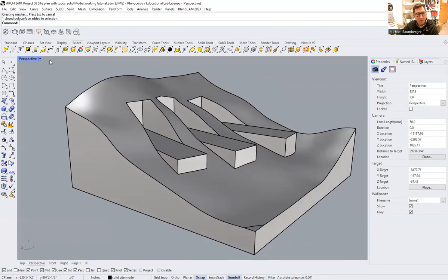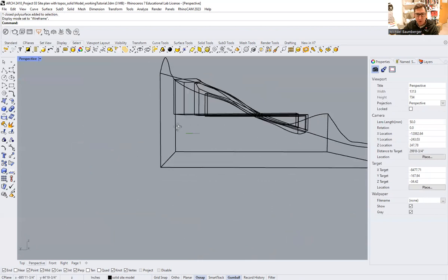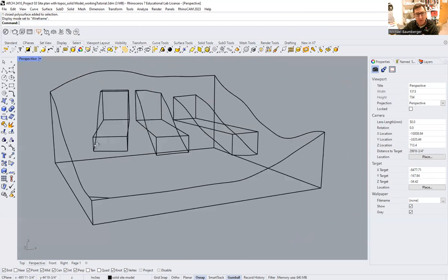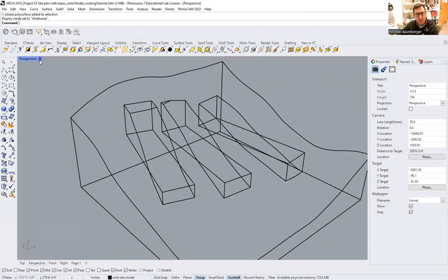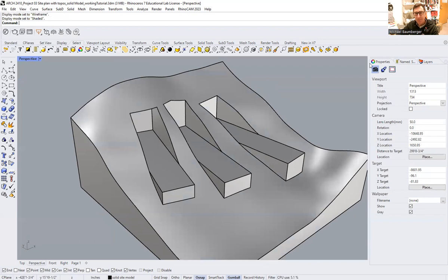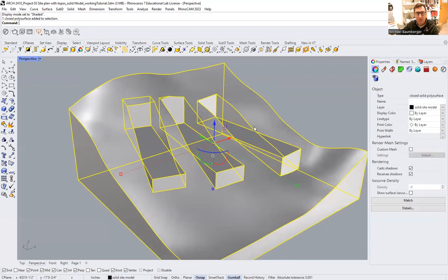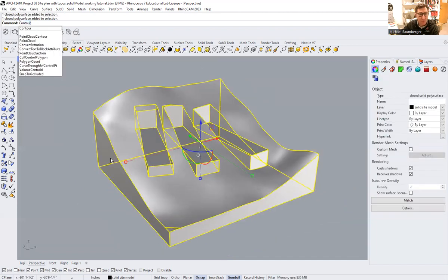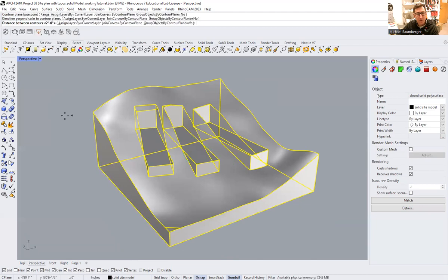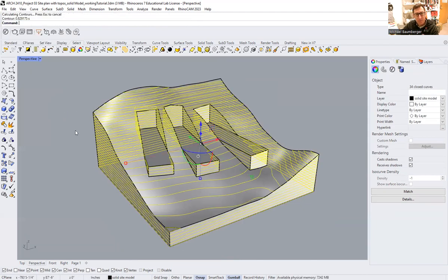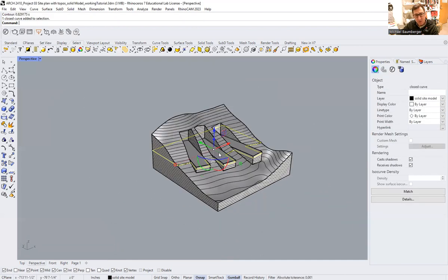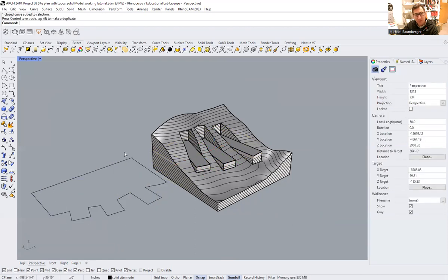And so the best way to look at this is through wireframe, right? We can see that there's no longer any intersecting objects. It's all just a series of surfaces that produce a closed solid poly surface. So now that we have this, I'm going to contour one more time. All right, same parameters. Now this time when I select a contour that intersects with these other elements, everything is contiguous, and that's really important.